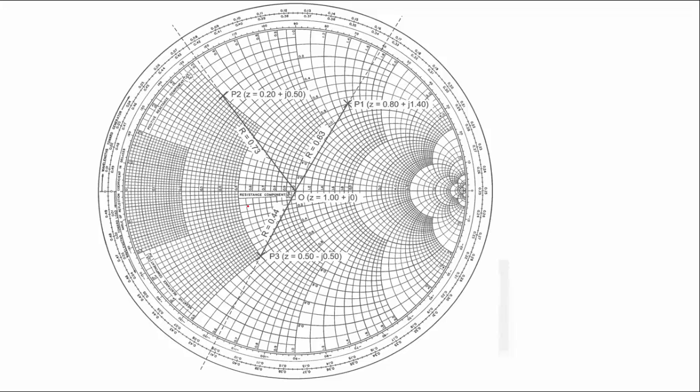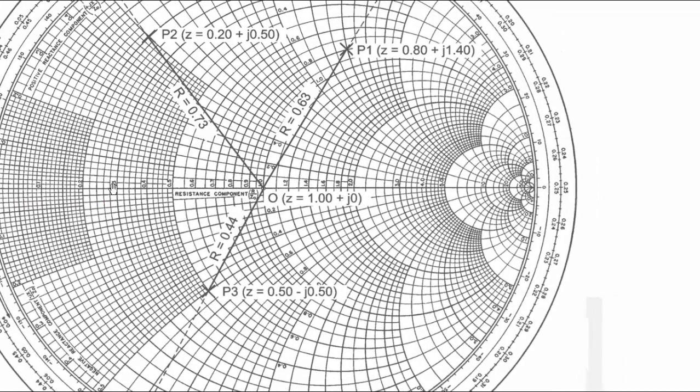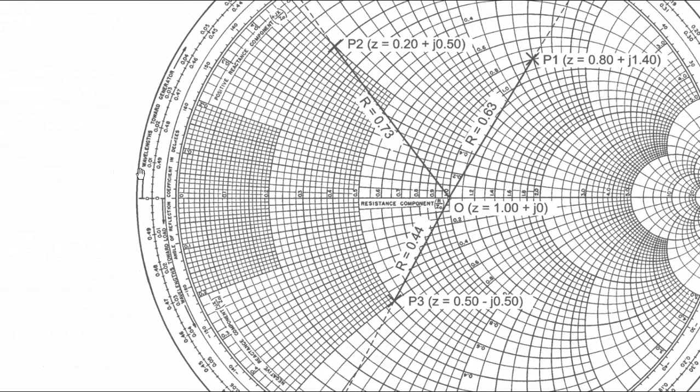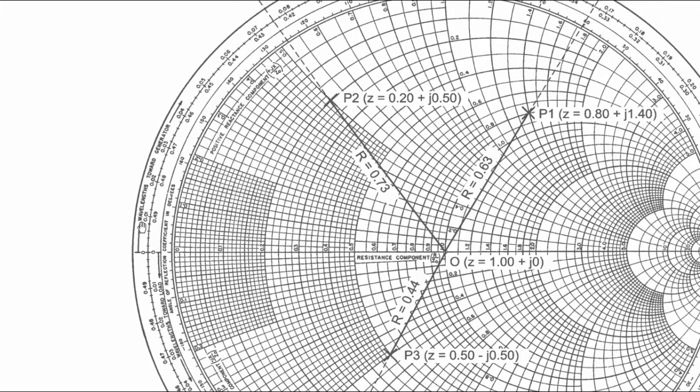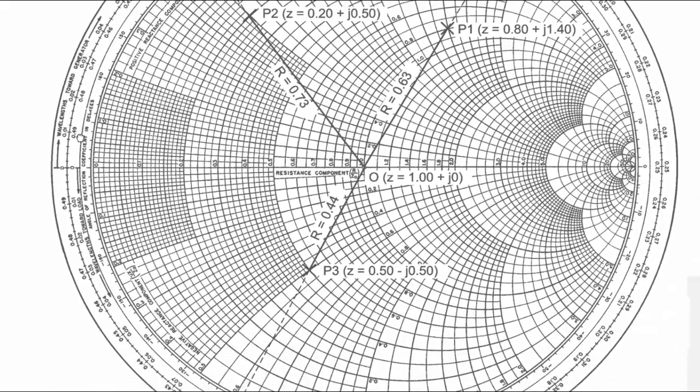So this is the actual Smith chart with the actual scale. The outermost circle is marked in terms of wavelengths. If I could just zoom, okay. See, the circle next to the outermost circle, the penultimate one, we have wavelengths depicted here. So this is 0.01 times the wavelength, 0.02 times, and so on.